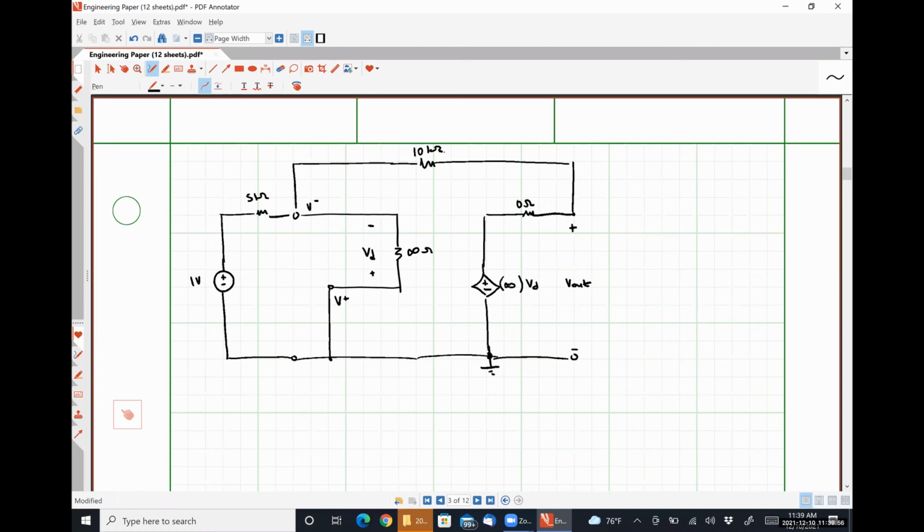So before we even start doing our analysis, Brandon, what's up? The same assumptions that we made for the comparator circuit. Our Rn to be approaching infinity, our AV approaching infinity, our R out to 0 to have a perfect comparator circuit.